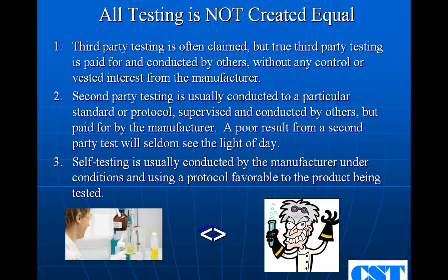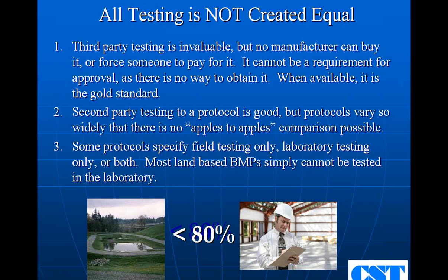Self-testing is usually conducted by a manufacturer under conditions and using a protocol favorable to the product being tested. There's one famous baffle box out there that was tested by a professor at a fairly obscure university using 2,000 micron sand. My goodness. If you can't catch aquarium gravel in a water quality storm, you probably need to be doing something else. But the point I'm making is all this testing that you see out there is not necessarily the same, and there's been an effort underway to come up with a kind of a level playing field.